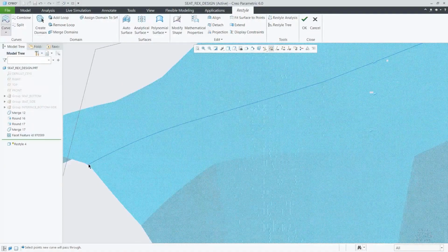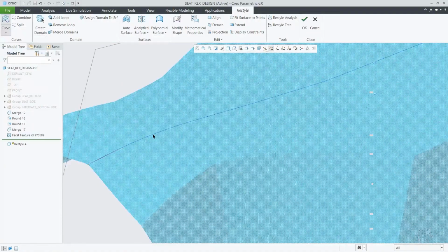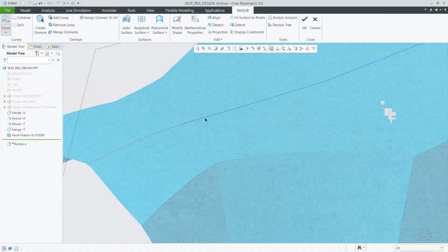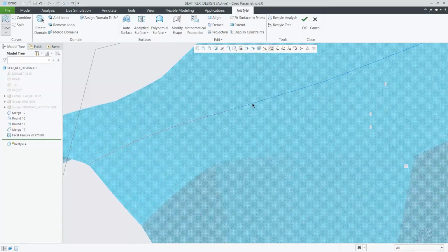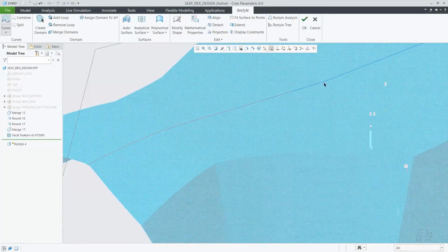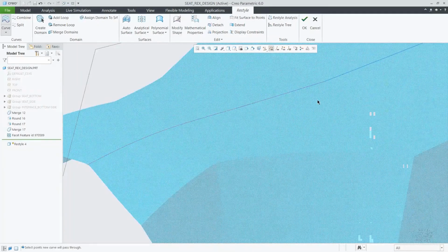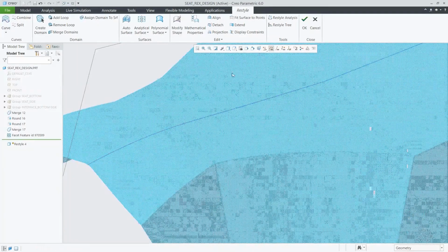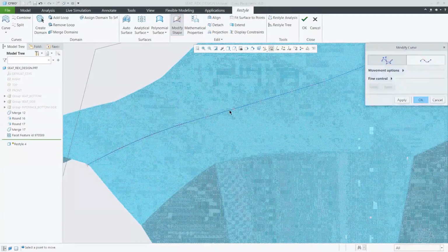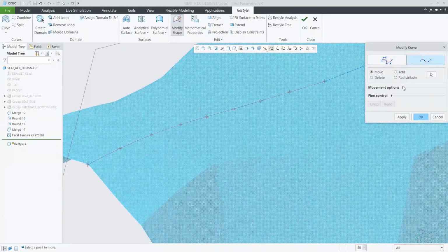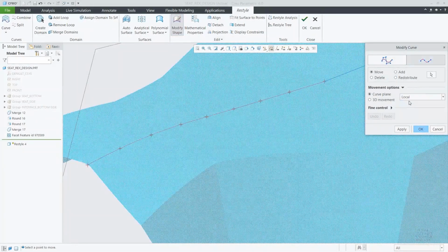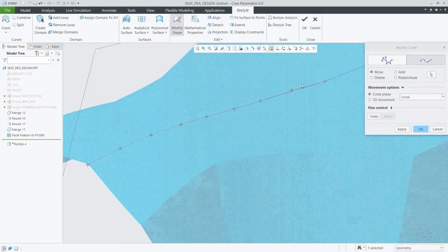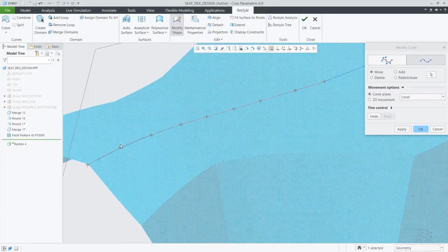This is what we're going to be doing over and over in this process: first building out the curves, defining the domain of points that we want to work around, and then creating surfaces to outline that geometry that we have from the point data. This first curve is going to be along that section curve, and it's going to start along the initial surface, but you have many different options for taking those points, modifying them, and making them into whatever shape you need. So you're starting with the point cloud, but you're not stuck with it.